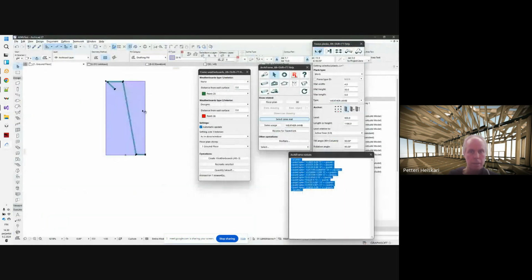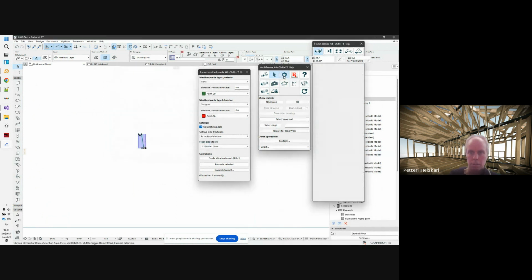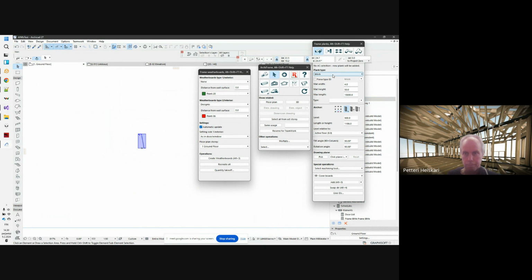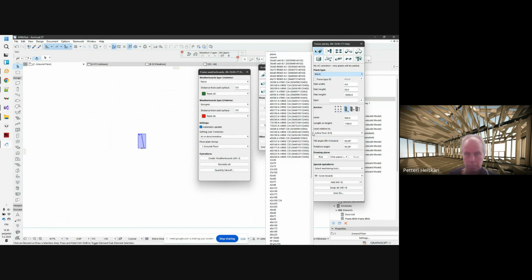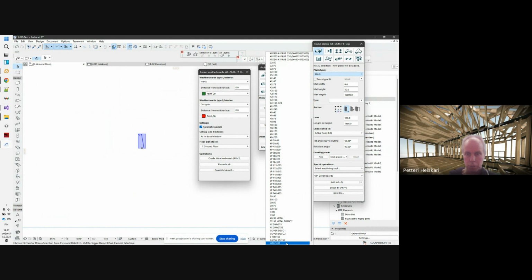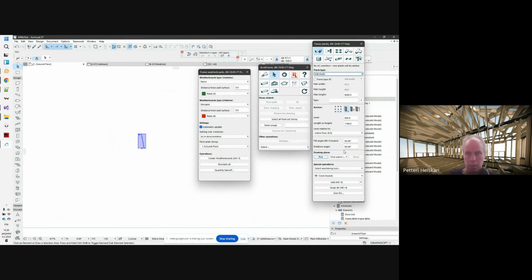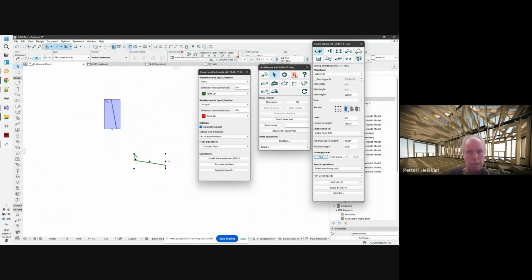the definition, and then in ArchiCAD, reload the settings, and then remove selection, and let's see how does it look here. So it is at the end of the list, and I'll place it 0 rotation as a column, 90-degree angle, 0 level. So there we have it. The profile is the same, and the orientation of the profile is actually looked from below this piece. So that's why it looks mirrored to this one.